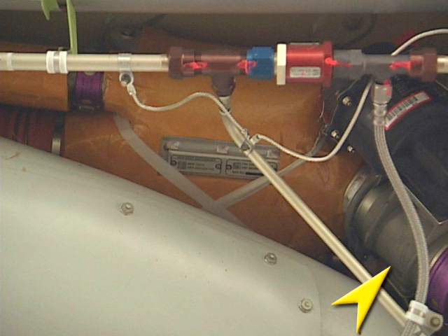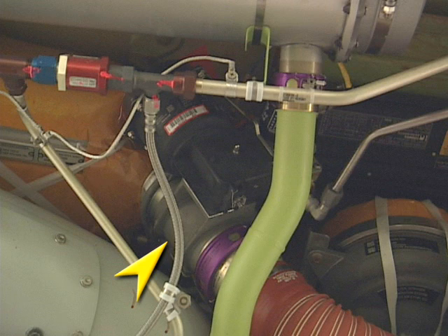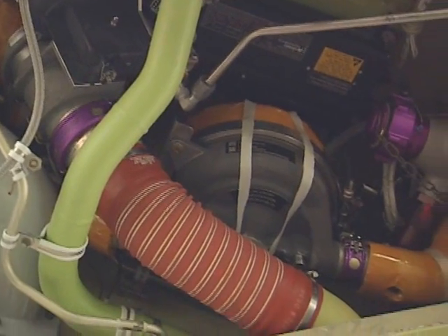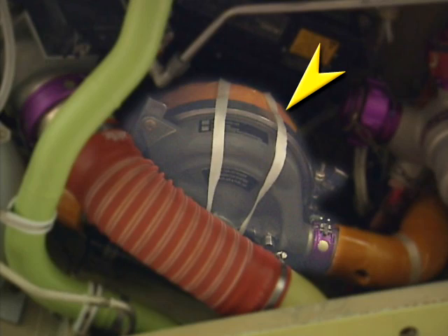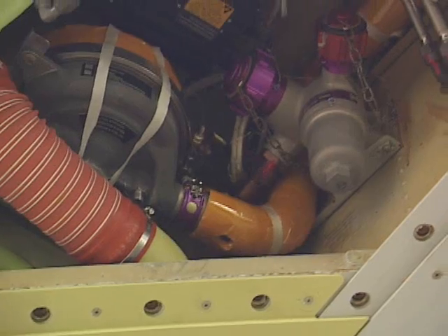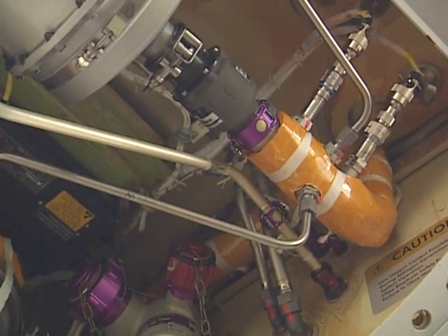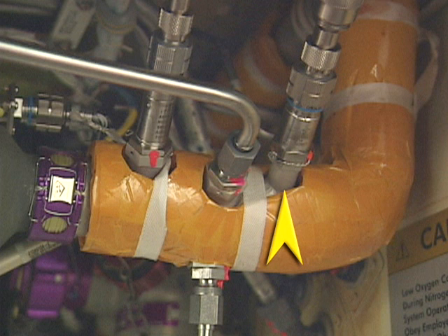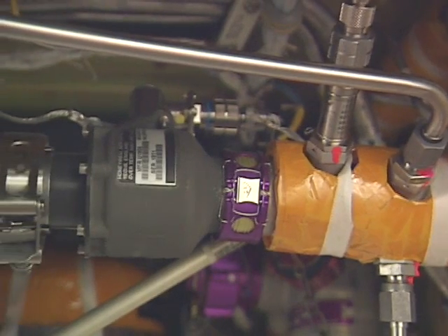The NGS ram air valve is between the heat exchanger and the ram air exhaust duct. Next is the filter. Then the air supply duct leads aft, outboard, and then forward again to the temperature sensor. Let's move up for a closer look. And then to the thermal switch. Then to the over-temperature shutoff valve.